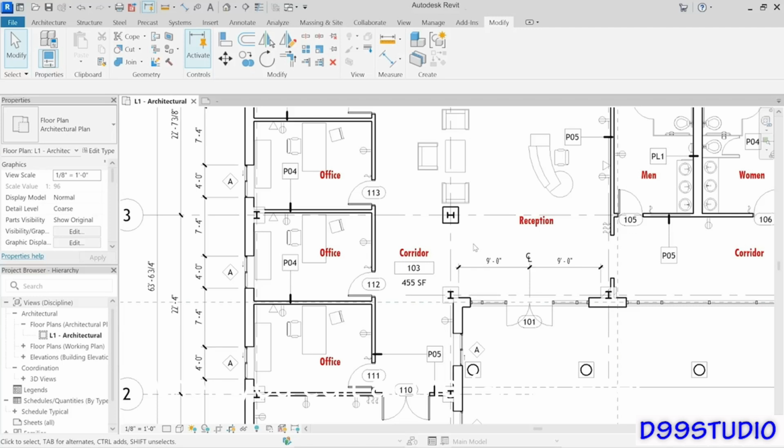When you edit at the family level, it will impact all instances of that family, not just the ones of a particular type and not just the ones that are selected. So each time we're moving up the hierarchy, you can see that it's having more and more impact globally across the model. Now, that brings us to category, our final highest step on the hierarchy. And to show you a category level modification, I'm going to switch categories now.